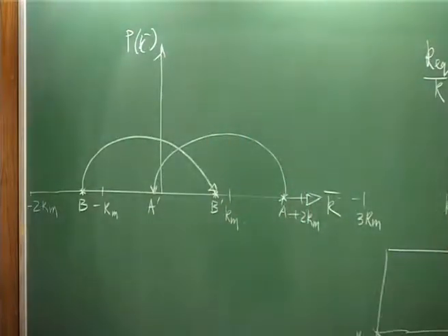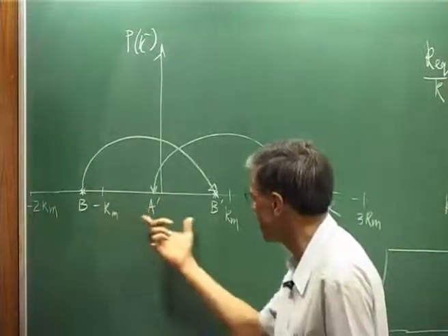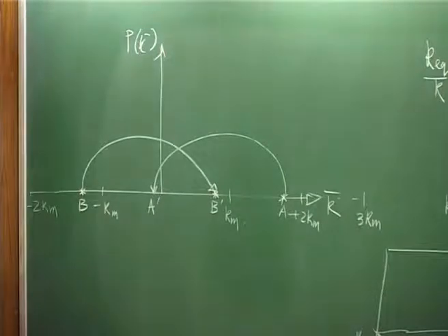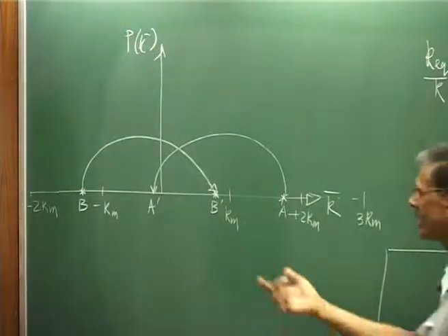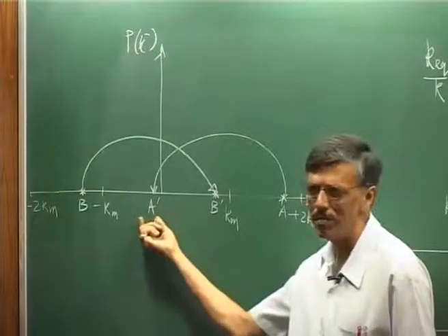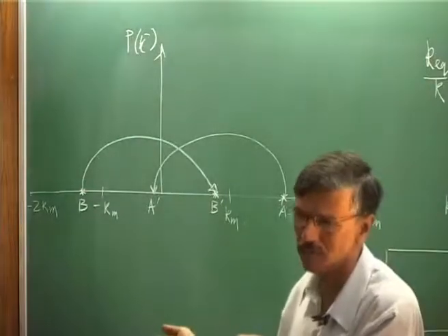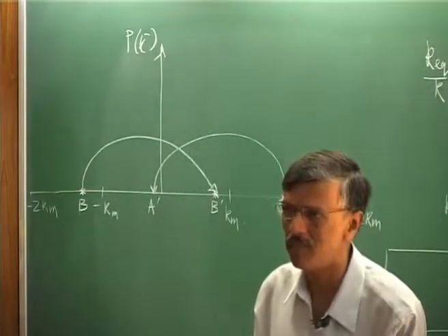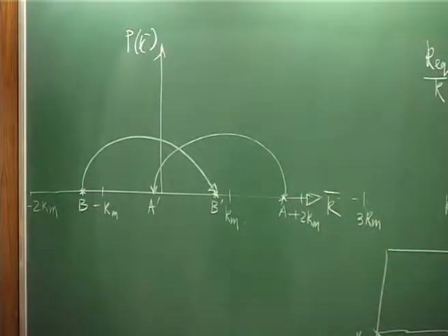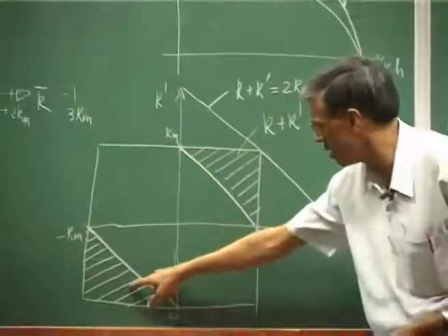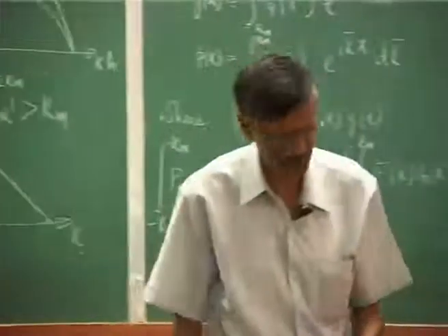So, what is happening is, you are seeing that all these points in the admissible range are also getting spurious, erroneous contributions coming from outside, and they are mapping inside. So, this is the dictionary meaning of aliasing, that this B prime or A prime should not be there, but they are spuriously taking the role of those points. That is what is called aliasing, right. So, you know the source, because we have this region that is getting mapped inside, this region is getting mapped inside, and we are getting the problem.